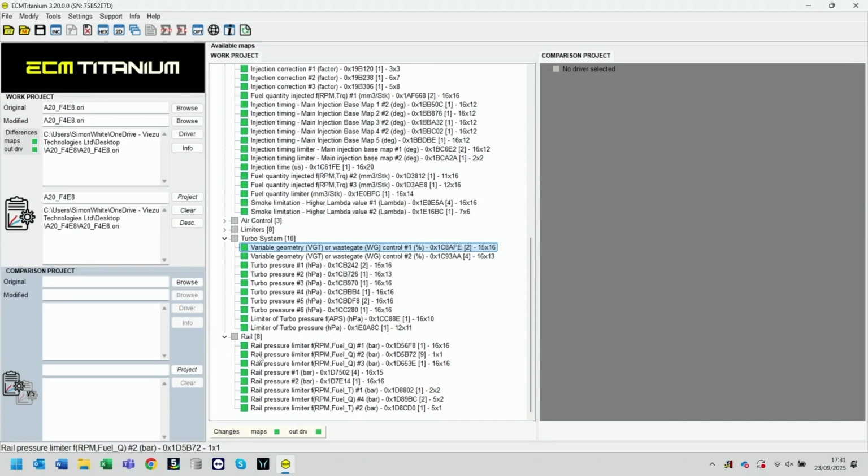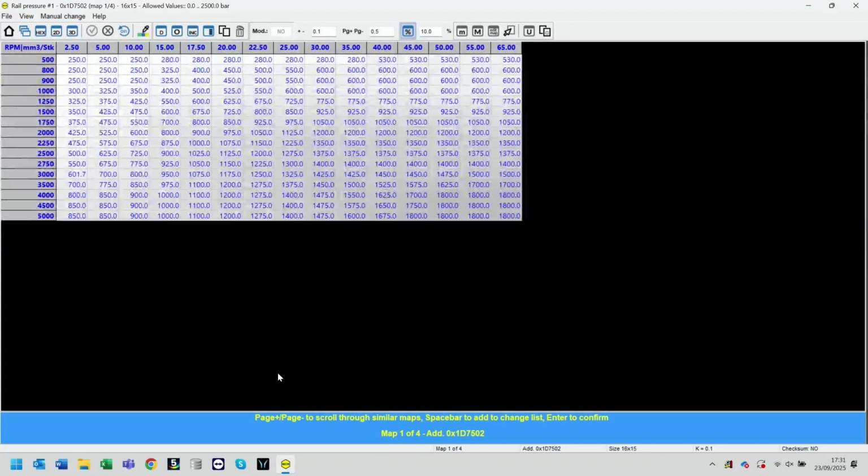And lastly, into our rail pressure. We're going to look at our rail pressure map before we look at our limiters. And if you're keeping up with this or watching it back on YouTube, pausing, taking some notes and watching the next bit, which is highly recommended of course, you'll see we have 1,800 bar of pressure in the bottom right hand corner of the map, which ties into our injection time map or injection duration map or pulse width that had 1,800 bar of pressure for the control, the scaling on the axis there as well. And what does the map show in the top, Paul? It shows 65. It shows 65.